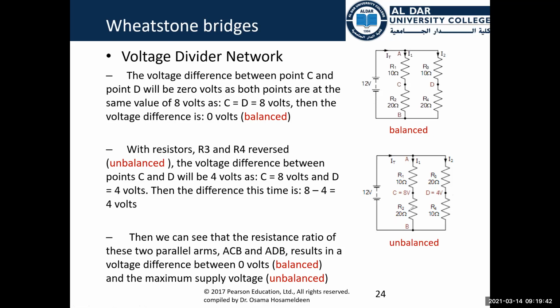The voltage here is 10 over 20 plus 10, which is 1 over 3, times 12, and this is going to give us 4, right? So this is not 8. I will fix it. It should be 4, not 8.